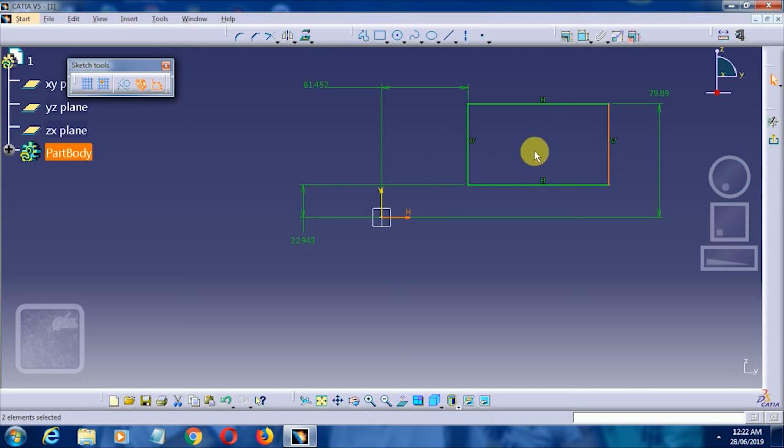So if we want to give a length, we always have to make sure that a vertical line is represented by a vertical line, or we can use another vertical line as well. Now guys, as we have learned in our college days, there are two types of system, that is the incremental system and the absolute system. The absolute system works from the origin, whereas the incremental system works from the latest point from which we can draw up dimensions.